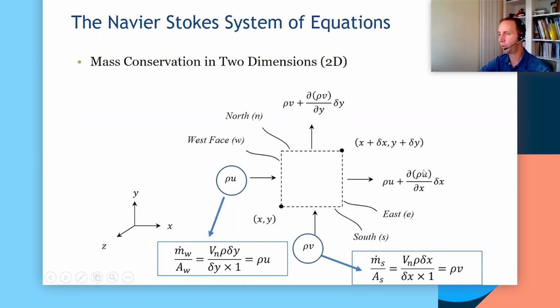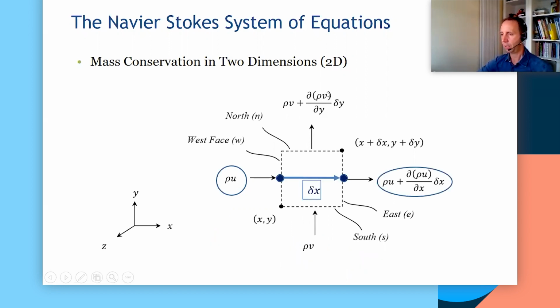Okay, so if you look at this, take the rate of change multiplied by the change, the delta x cancel out, and you get your rho u plus the change in rho u, d rho u. You do the same for the bottom. So we extract the normal component to the face for the velocity, which is the y component of the velocity vector, right, and v rather than u, and we do the same for the change. Okay. So that's what's explained here. We changed by delta x, and therefore we got that change.